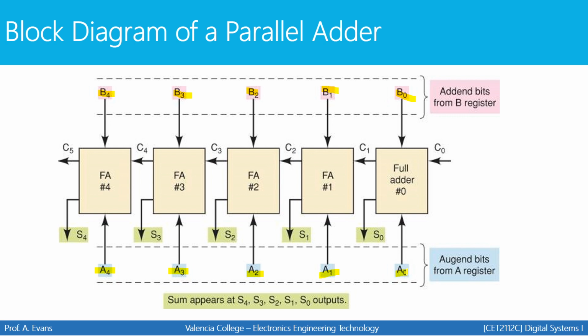So what we want is a full adder circuit that can basically take input A0, input B0, possible carry coming in, and determine the carry going out plus a sum. If we string these together, all of a sudden we have a circuit that can perform addition. And all we need is one full adder for each bit in your number. So a 10-bit number would need 10 of these, a 100-bit number would need 100 of these, etc. But it's a circuit that would add up your two inputs plus your carry coming in and determine your sum and your carry going out. So we're going to design that.